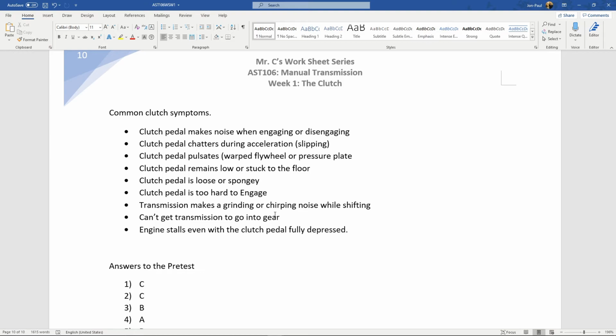This is the beauty of this, and this is where I want to comfort and calm you a little bit, because I know we're going over a lot of stuff, but diagnosing this is very simple. If it is the clutch, the flywheel, the pressure plate, or the throwout bearing, there's no way to verify without removing the transmission. So I think it's the clutch. What I gotta do? Pull the transmission. I think it's the pressure plate. What I gotta do? Pull the transmission. I think it's the flywheel. What I gotta do? Pull the transmission. So even if I'm wrong, I still gotta pull the transmission.